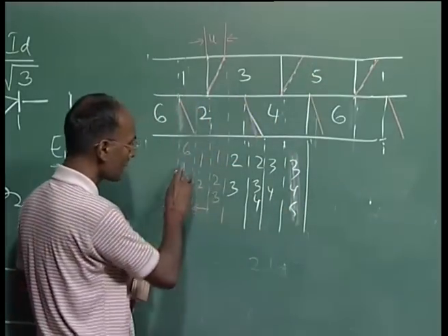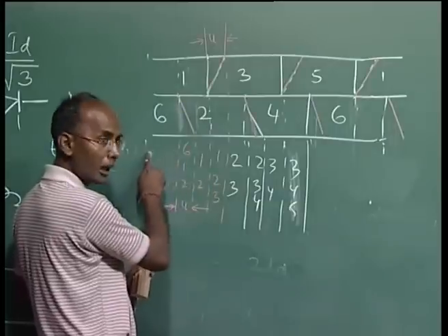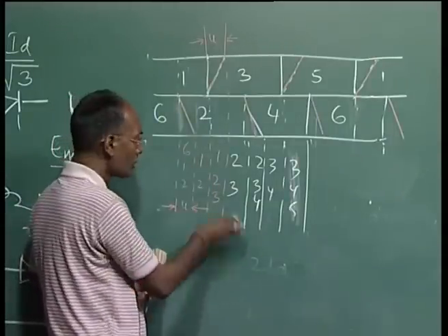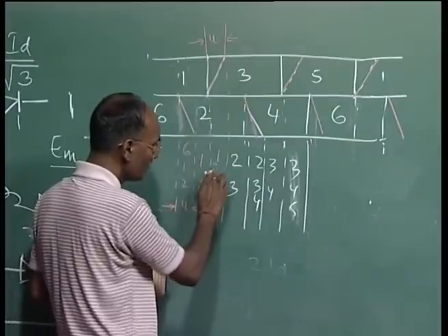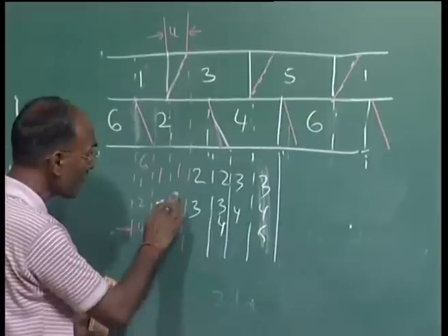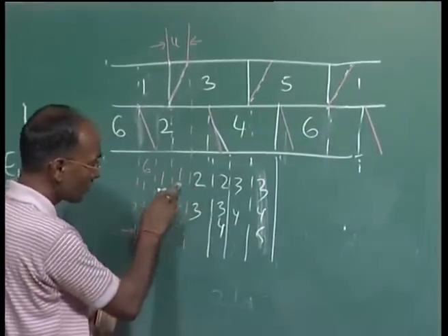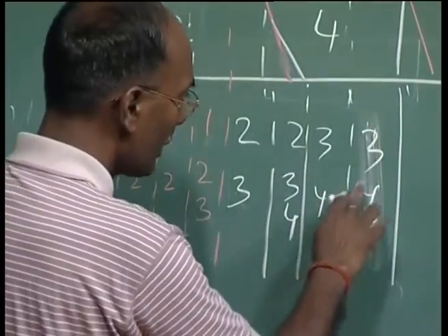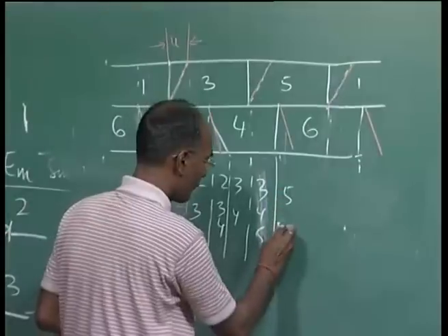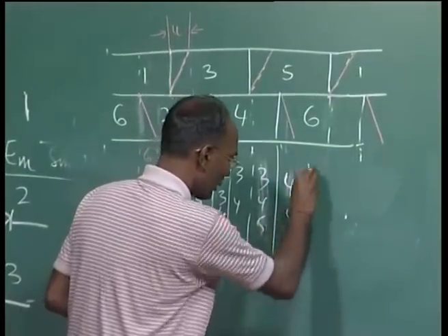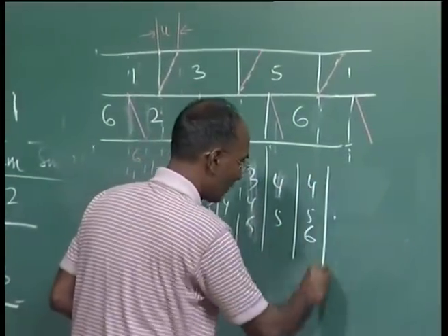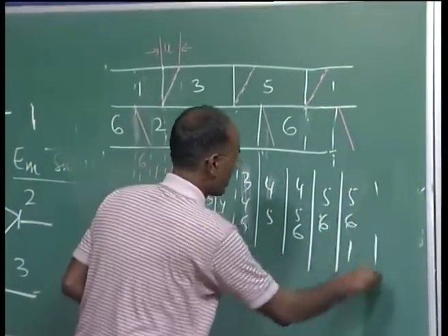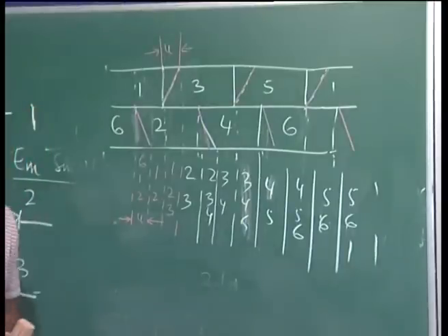But in the sequence pattern we are getting 6, 1, 2, then 1, 2, and 6 will be off because 6 and 2 are in the same commutating group. So, here this 6 will go away. So, 1, 2, then 1, 2, 3 here, then 2, 3, because 1 will be off as 3 is taking over. Now 2, 3, 4, now 3, 4, now 3, 4, 5, now we will get 4, 5, now 4, 5, 6, and then 5, 6, and then again 5, 6, 1, and so on and so forth, because again we are coming back to this.